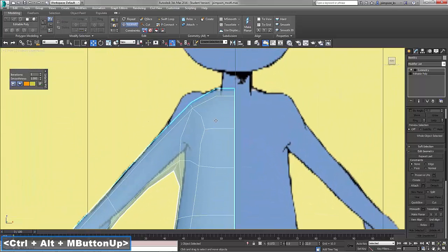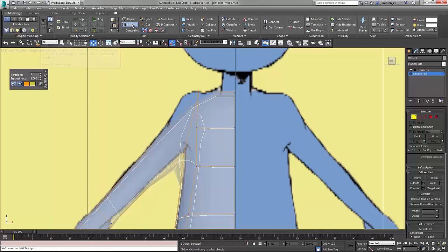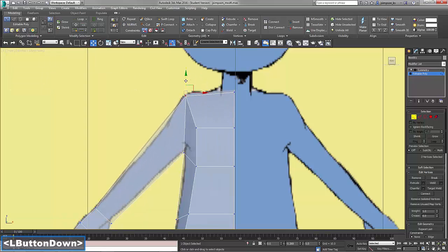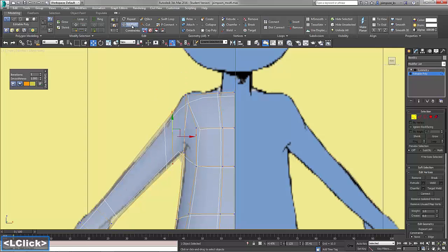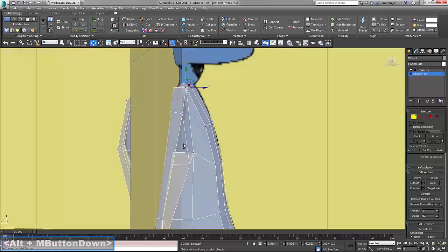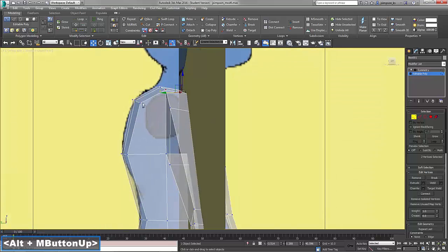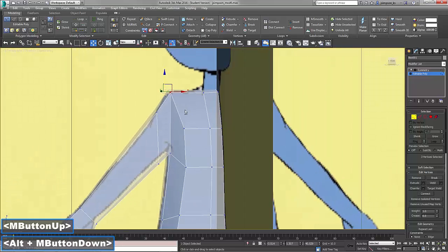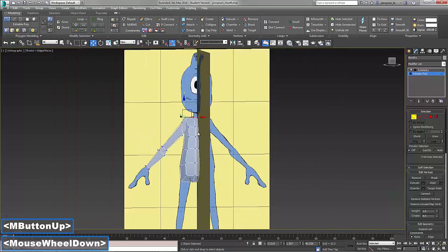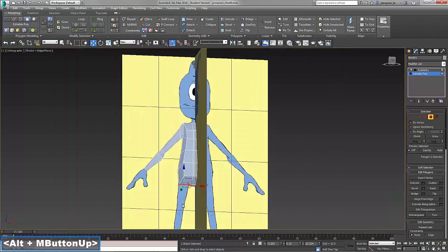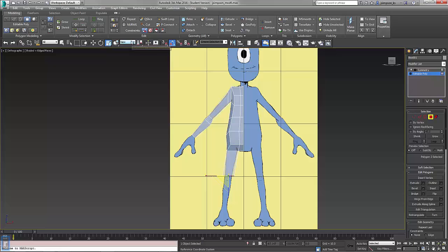In the ribbon, reapply NURMS. With NURMS active, we now have issues with the model. In vertex mode, move the vertices near the shoulder to better match the image. Close, but still no cigar. From the ribbon, select the Swift Loop tool, add 2 loops near the shoulder and adjust the vertices to match the image. Now that looks better. Switch off NURMS, as modeling with NURMS off is much easier. We will now repeat the process to create our character's leg.